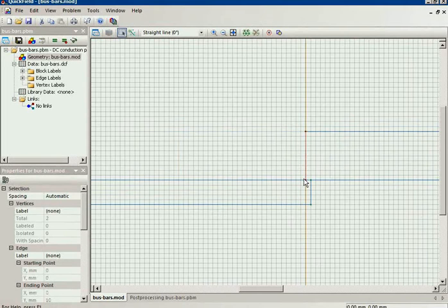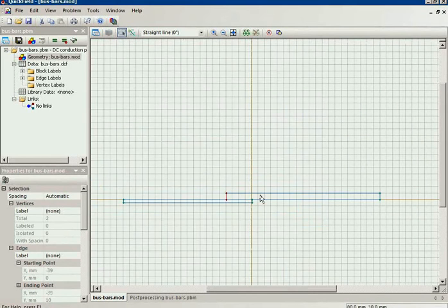I don't know yet. Because if I increase the contact area, at the same time I increase the length of the steel bus bar, and the resistance for the current will increase.